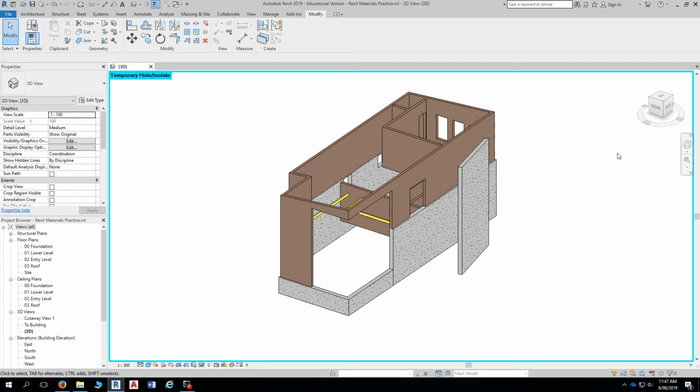Agreed? If I then want to change the colour of the internal faces, how do I do it? You paint them. This would be a classic example of where you would use the paint tool, assigning a material by face.